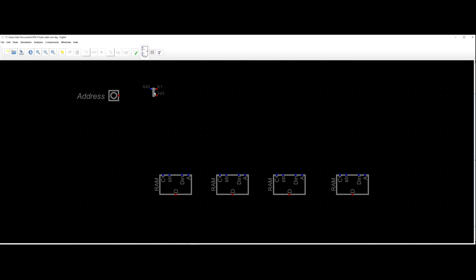So we're going to have an address which is 24 bits, and we're going to need a splitter because we're going to need to look at the 2 bottom bits. So input is going to be 24 bits, and the output is going to be the bottom 2. I don't remember if it gives me the top or bottom there, but we'll try it and see what happens. Okay, that worked. Perfect. Wait, is that what I want? Yes, that is. 0 and 1 are the 2 low bits, and 2 through 23 are the high ones. So I still get my address out here.